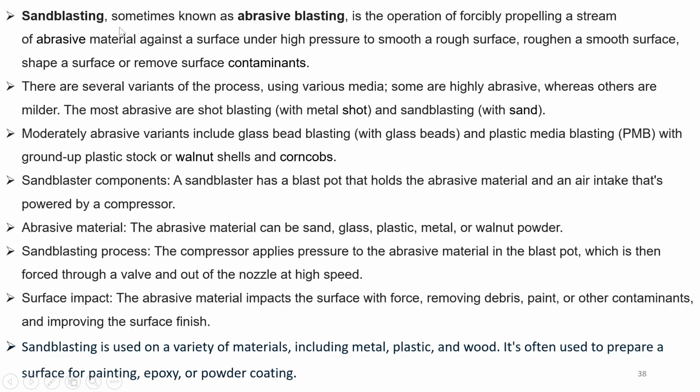Next is sandblasting, sometimes known as abrasive blasting. It is the operation of forcibly propelling a stream of abrasive material against a surface under high pressure to smooth a rough surface and roughen a smooth surface, or to shape a surface, or to remove surface contaminants. There are several variants of this process using various media.